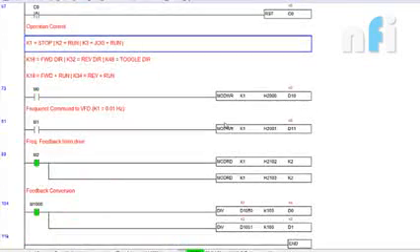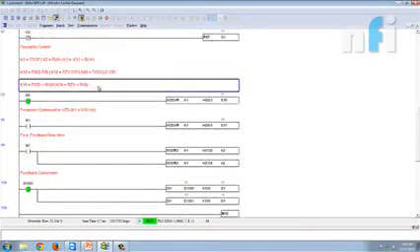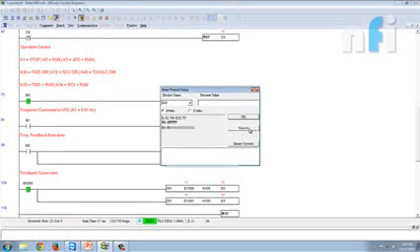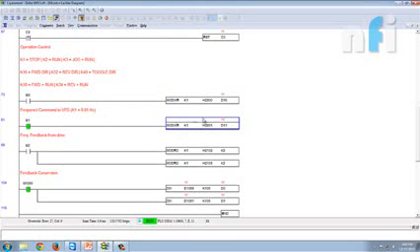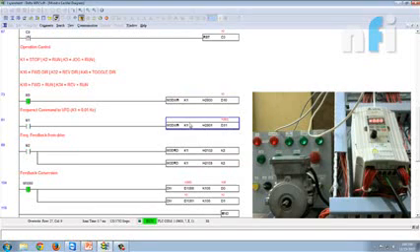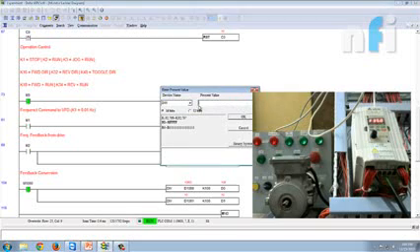Now coming to the Modbus write, this is the mod write M0. So here it is K1. K1 says motor stop. Let me put K2. Okay, before that let me put some frequency so that I can see the motor running. So right now it's K0, frequency 0. I'm putting K3500. We'll find frequency 3500. Hold on. Here you can see 3500. That is the commanded frequency.